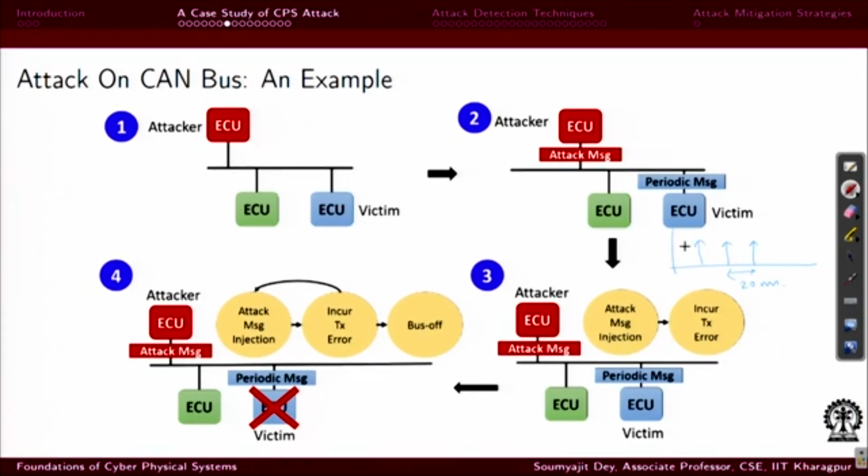So this is a periodic data stream and there may be an offset, right? Of course, the first value may have a phase, like phi. So let's say for every kth message, the transmission time is phi plus k times 20, right? The issue is this phi is unknown to the attacker. So what is important is the attacker needs to first synchronize with this victim ECU. There are techniques for doing that. We are not discussing that here.